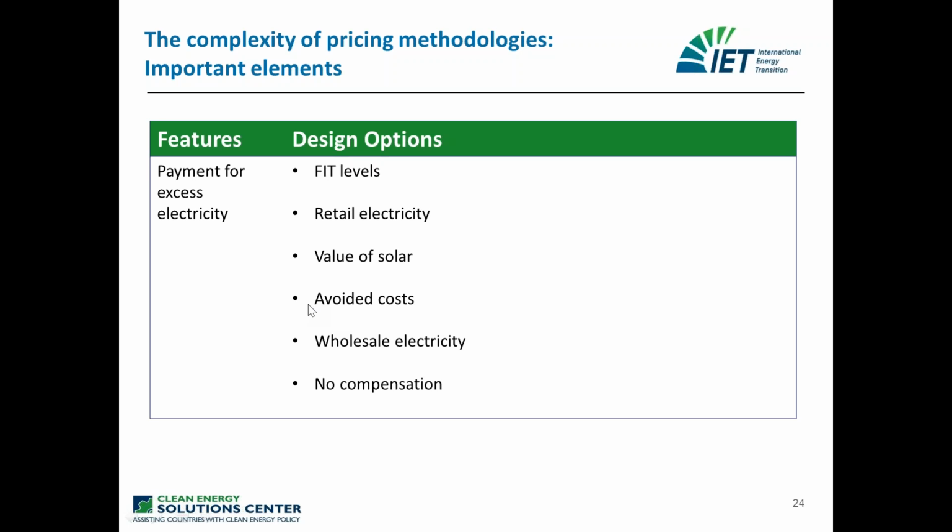So you look at the avoided cost of the utility and then say, okay, for each and every kilowatt hour that is fed into the grid, which is in excess to my own consumption, I only receive a price in line with the avoided cost of the utility. This, of course, makes the utility normally quite happy, because they're no longer being penalized for operating this net metering system, but can just integrate these additional kilowatt hours that they get under the net metering scheme into their systems based on the general cost calculations that they have.